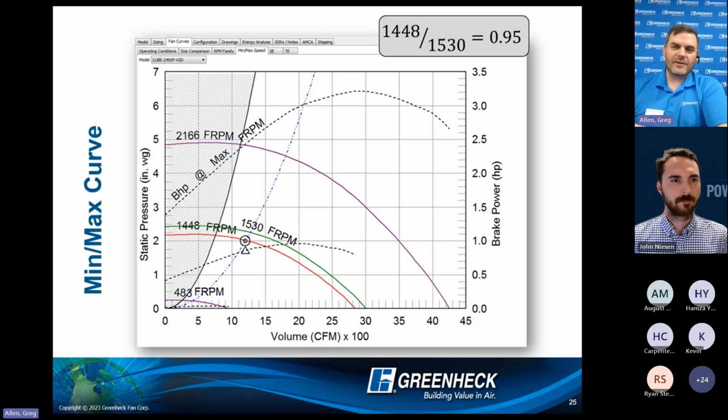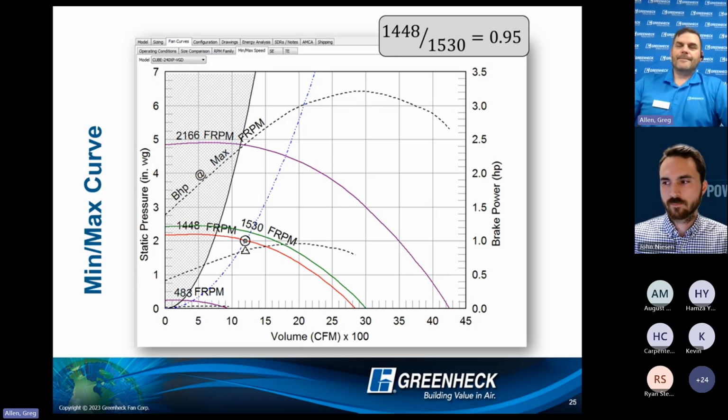But they all use 0 to 10 as that carrier. And really that ties across to when I employ VFDs as well. Most every VFD I deal with accepts a 0 to 10 volt signal as well. So really the same controls can control EC motors, VFDs, right? So I'm kind of on the same platform.